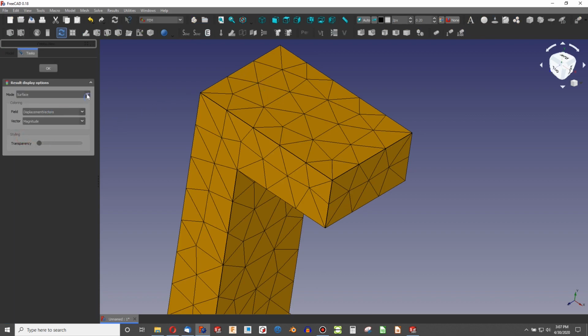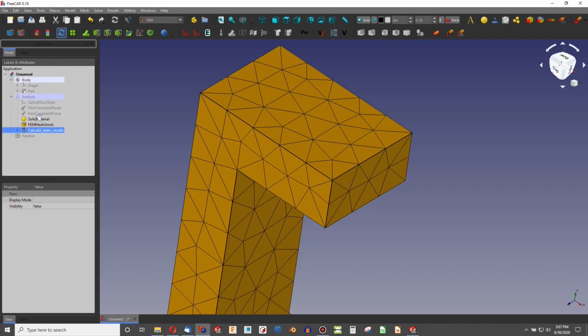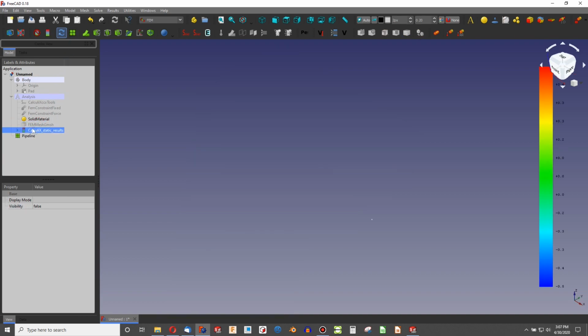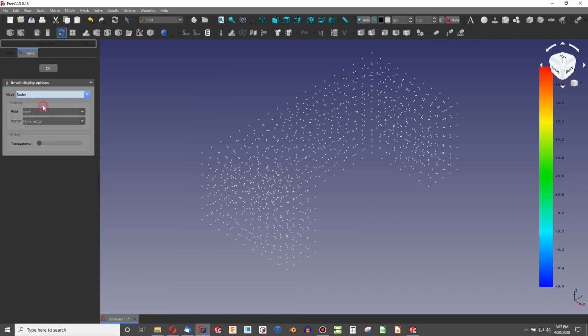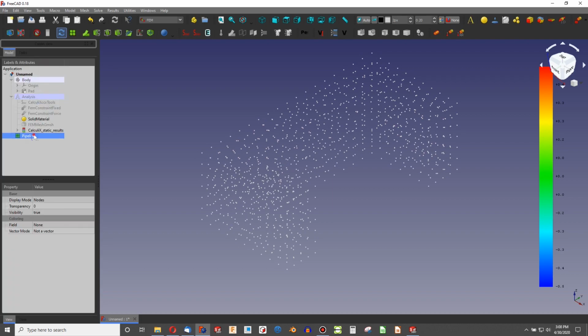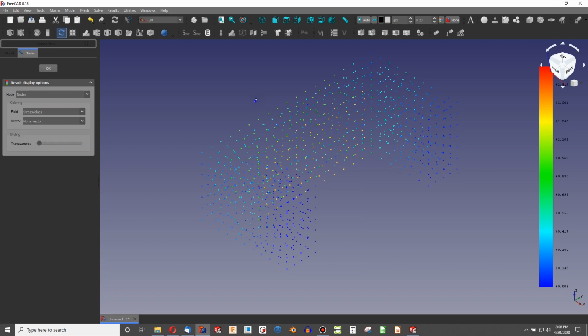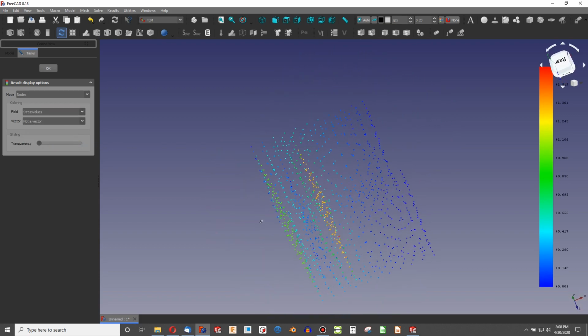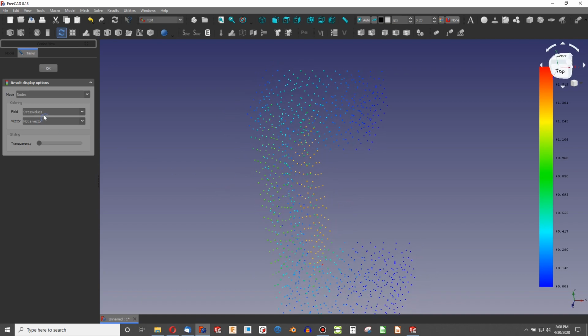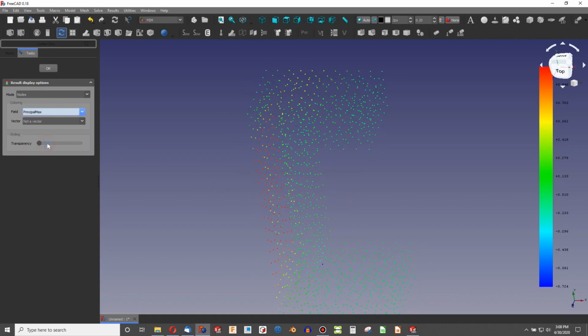And if you'd rather see the kinds of places that we've made a calculation in pipeline, we can reference nodes. And let me turn off my mesh here. There we go. So in pipeline, we can reference nodes, and we can go with stress values in those nodes. We can say at every point a calculation has taken place as to what our stress value is. So there's our principal max or shear, all sorts of things.